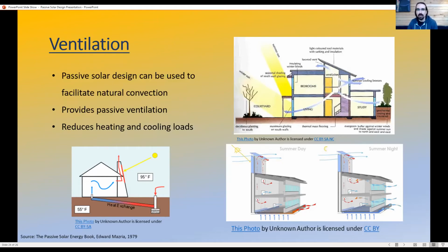In these situations, you can see here we have what is like a chimney, and in this drawing, that's this channel right here. As the sun strikes that and heats the air up in that column, it is exhausted through the top and then pulls air in through the bottom to make up the air that is pulled through the space.